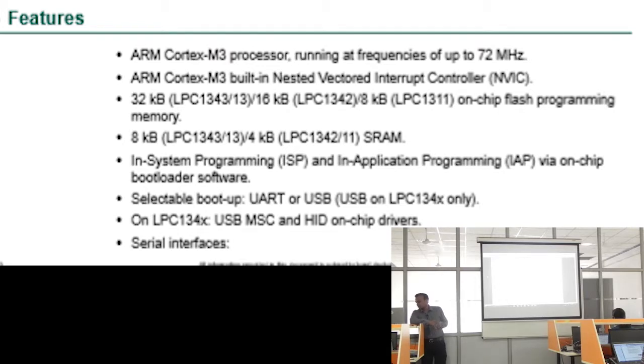Next, there is something very important called a nested vector interrupt controller. Have you used it in ARM7 TDMI? The vectored interrupt controller? You have used it, right? In 8051, when you did programming, there were different interrupts: reset interrupt, GPIO interrupt, timers, etc. All those interrupts were given priorities, correct? Reset was given the highest priority, and the priorities go on changing. Now in an 8051, those priorities are fixed.